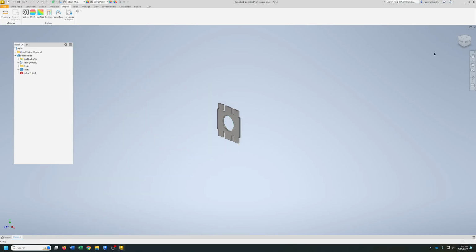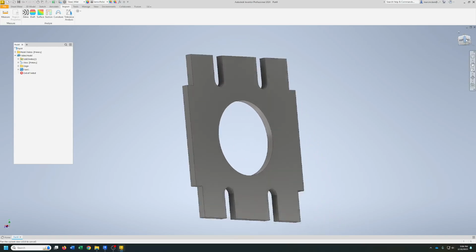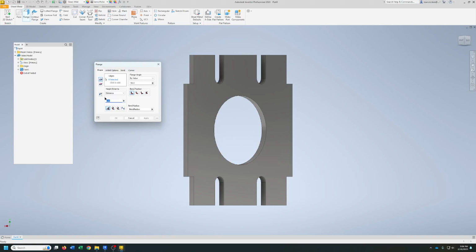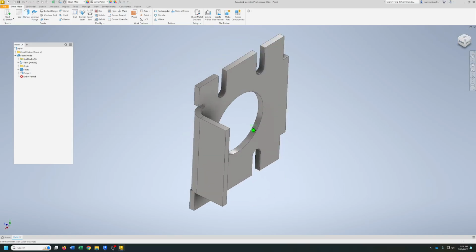Now, we're going to do our flanges. So what we want to do is we want to turn this back this way so we can see the back edge. Okay. Go back to sheet metal, go to flange. We want that to be a 1/2 inch long. All right. Unfold options is good. Bend is good. Corner is good. Go back to shape. 0 selected. We're going to pick just this one. Okay, made that flange. Bang. There we go. So here's our flange.